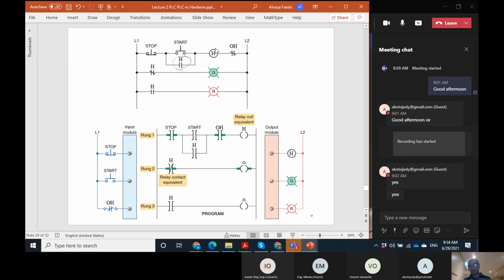This is the way that we use that. We use the auxiliary contact of this. The state of this is exactly equal to the state of this. I mean that when this is energized, this is closed. When this is de-energized, this is open. So something important about this auxiliary contact is that its state is exactly equal to the state of the coil of the contactor.